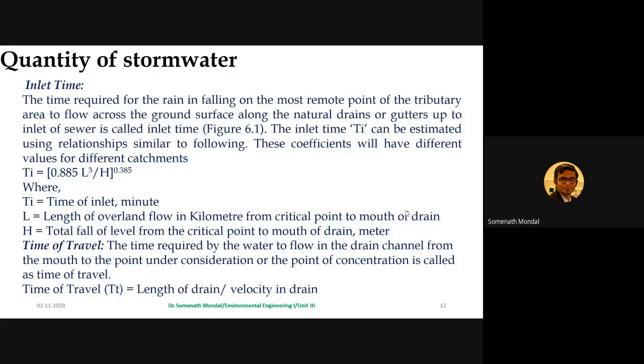The sewage is not a correct word for the waste storm water. So what is inlet time? We have discussed time of concentration and critical rainfall time, but now we need to talk about inlet time. Try to remember whatever terms I am discussing here, and understand the difference with other relevant terms. So inlet time is the time required for the rain falling on the most remote point of the tributary area to flow across the ground surface along the natural drains or gutters up to the inlet of the sewer.